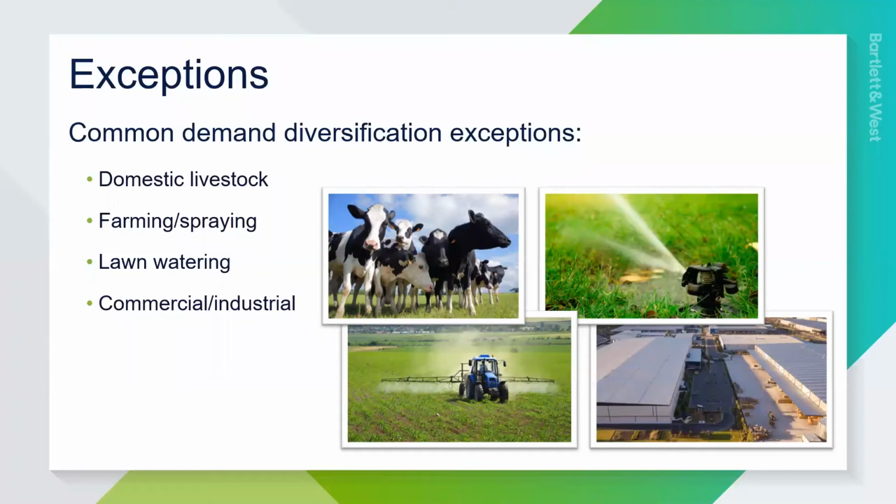In these instances, what we typically do from a modeling standpoint is we try to pull these out unless they are built into the demand diversification curve themselves. Some of that can get incorporated into those curves, or compensated at least. But another way we also deal with this that's more typical, or actually follows the usage patterns better, is we consider these base flows and pull them out entirely or aside from the demand diversification analysis and the curves you saw on the previous slide.